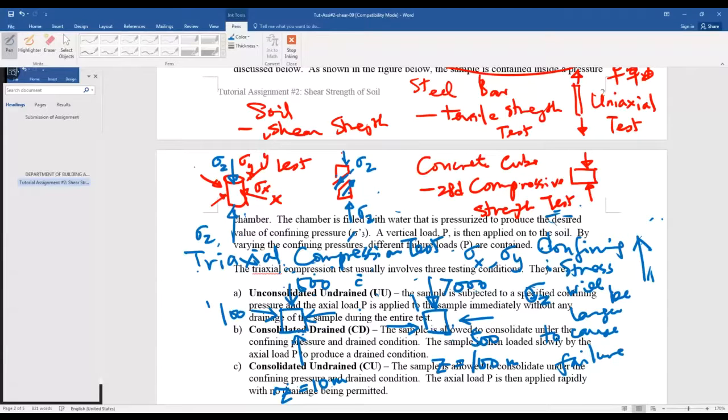In other words, we can put our building structure, right, with the foundation at that depth. So no matter how tall the building is, at the exact 100 meters, it can resist your loading failure because the confining stress is very great there. So you see what I mean? That's why we have to perform triaxial compression tests in many geotechnical laboratories for soil testing.